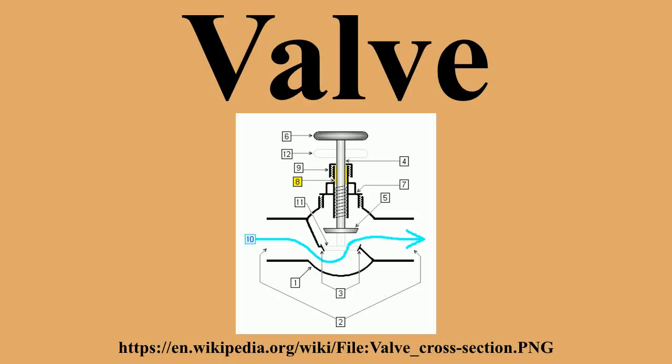Spring. Many valves have a spring for spring loading to normally shift the disc into some position by default, but allow control to reposition the disc. Relief valves commonly use a spring to keep the valve shut, but allow excessive pressure to force the valve open against the spring loading. Coil springs are normally used. Typical spring materials include zinc-plated steel, stainless steel, and for high-temperature applications, Inconel X750.